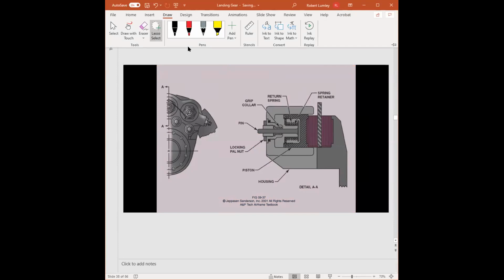I'm going to go through what's the purpose of the automatic adjuster. Well, the automatic adjuster is used to reposition the piston to compensate for brake pad wear. If we think about it, if the pads are brand new, the piston would be way back here.